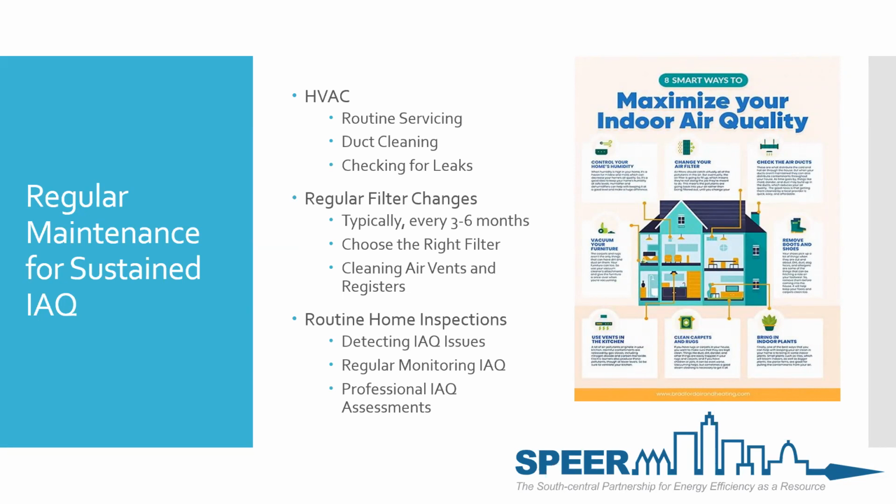And then, of course, you can have what's called a professional IAQ assessment. The value of the professional assessment is they do a comprehensive evaluation of the home and the air quality that's there. They may even set up sensors that have to be in the home for up to 72 hours, accumulating data throughout the days, the running of the home, the conditioning of the house, and how things are going through it. It's not just an instant. They can't just walk in with one device and say, yeah, you've got poor indoor air quality. I mean, there might be one that can do that in an instant because it's picking up something like CO levels or other issues in the air. But for longer term, you'll have something set up in the house to monitor it over time.